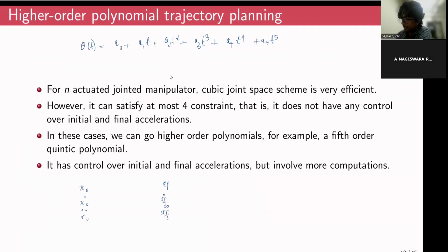So if you have a requirement of satisfying initial position, velocity, and acceleration, and final position, velocity, and acceleration, you can use a quintic polynomial.